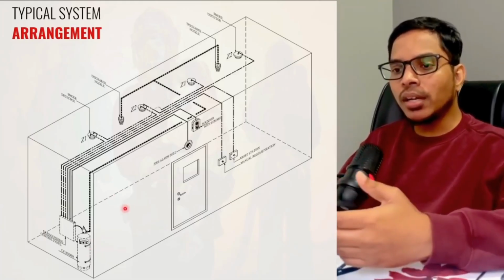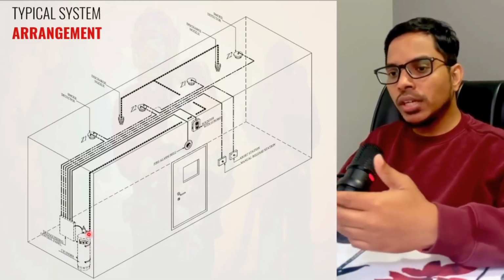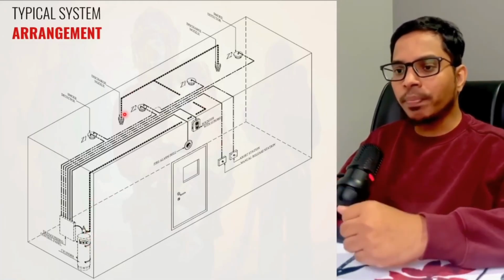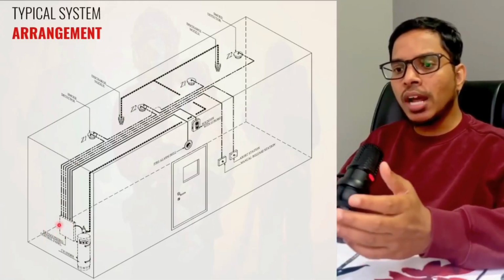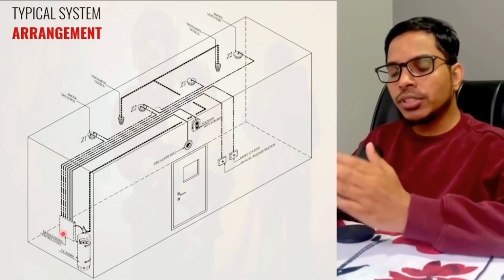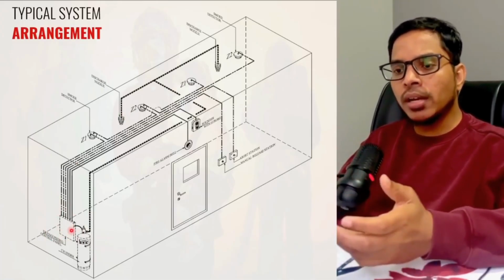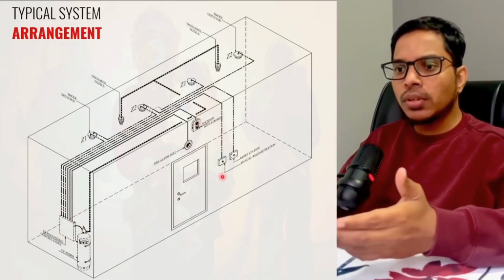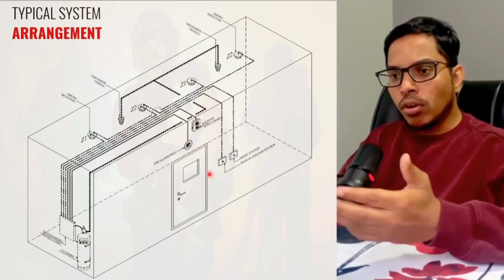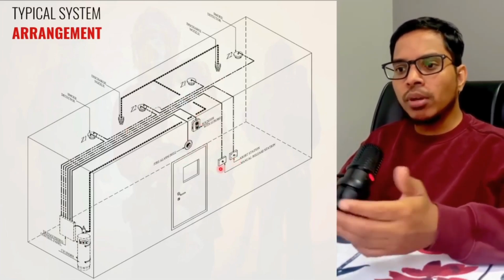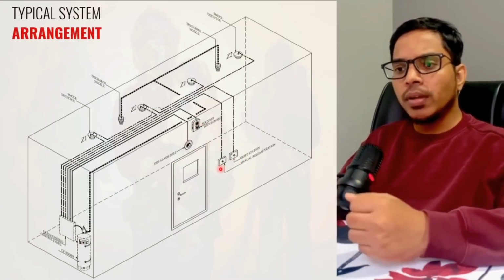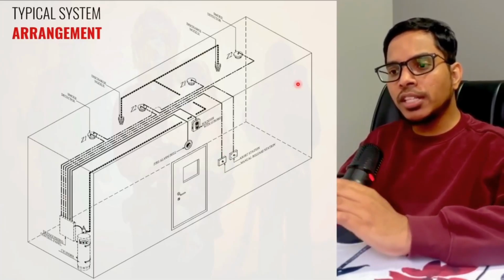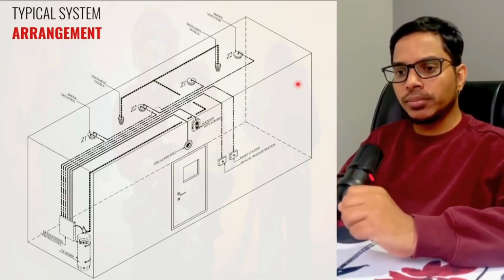In the mechanical part, you will have the cylinders, cylinder valves and also the piping network and nozzles, etc. In the electrical portion, you will have a releasing panel, which is also called an extinguishing panel, smoke or heat detectors, bells, horn strobes and strobes or horns, abort switches, manual pull stations, etc. So for now, please note this is a typical system arrangement for Cleanagent systems.